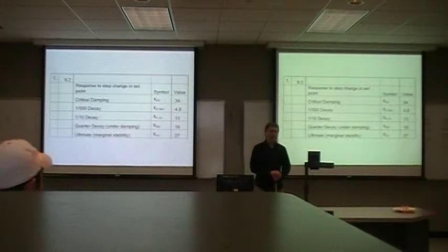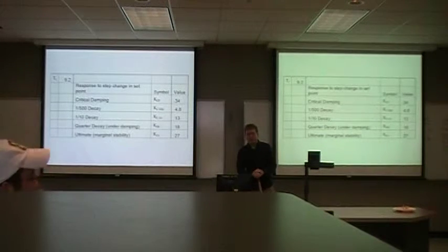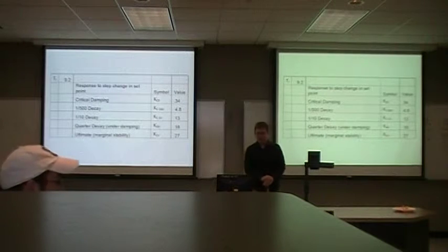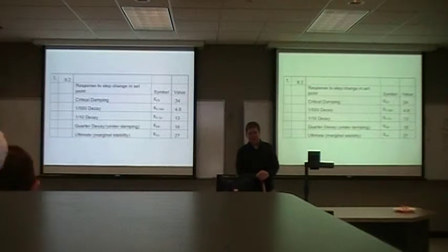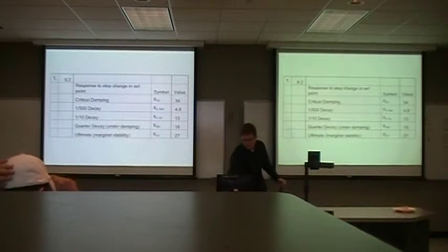Critical damping was 0.34, 1/500 decay 4.8, 1/10 decay 13, quarter decay 18, and ultimate was 27.